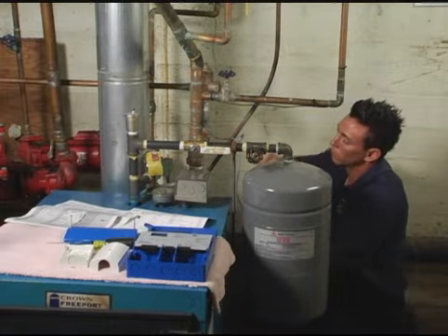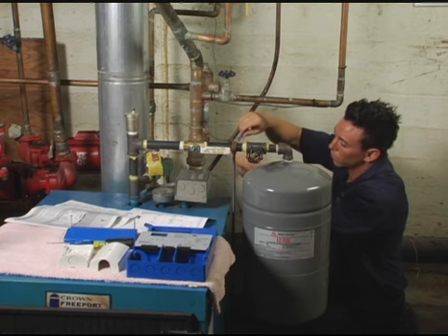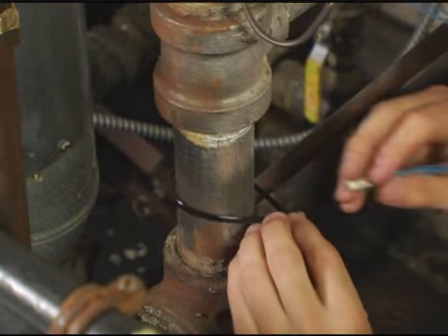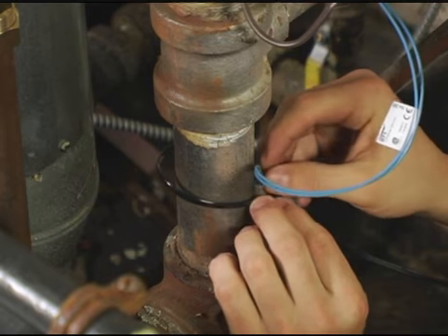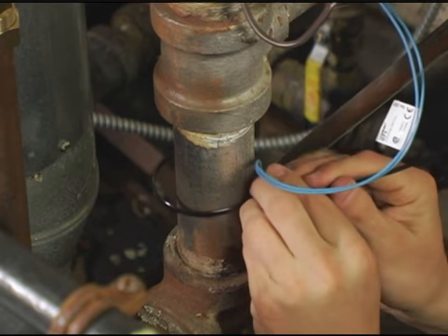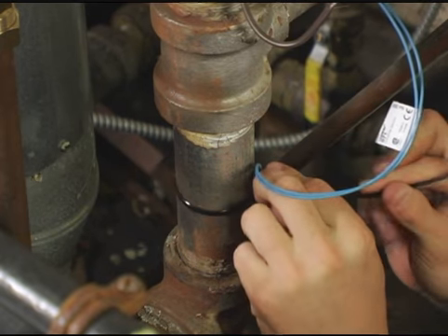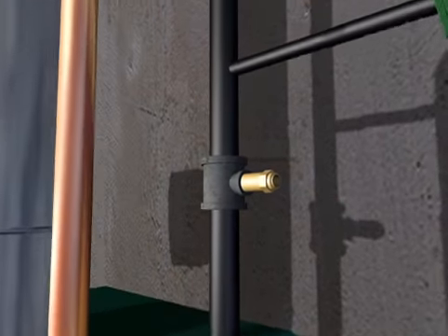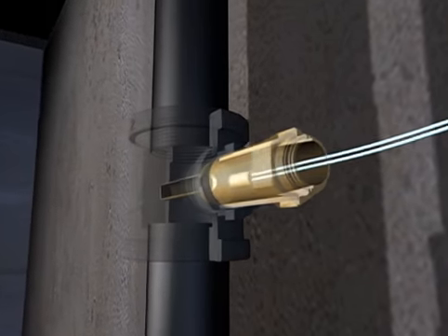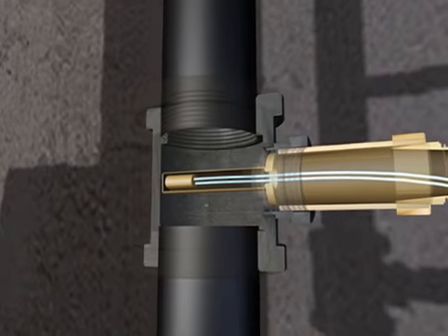The boiler supply sensor must accurately read the current temperature of the boiler. It can be located in a temperature well or strapped onto the piping. In some situations with larger steel piping, it is recommended that the sensor be installed in a temperature well instead of strapped to the pipe.